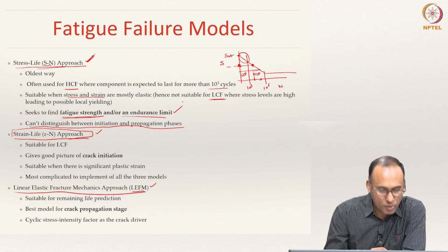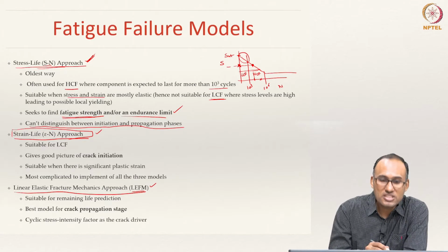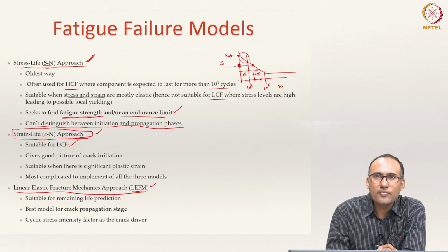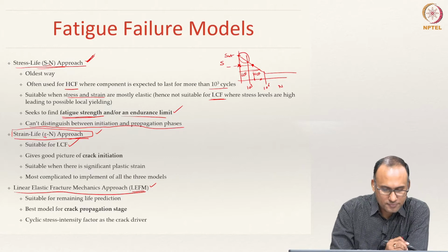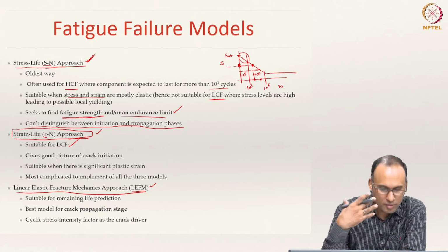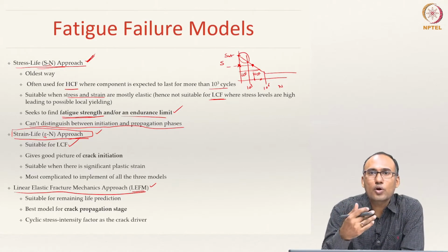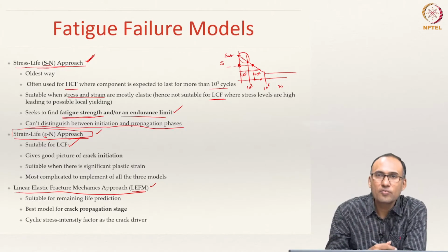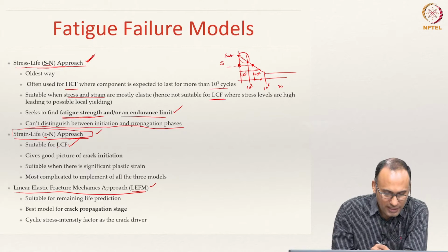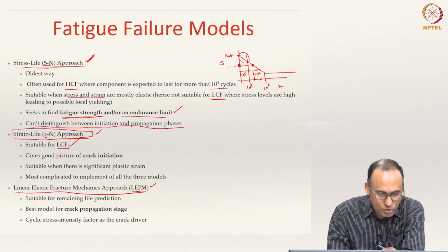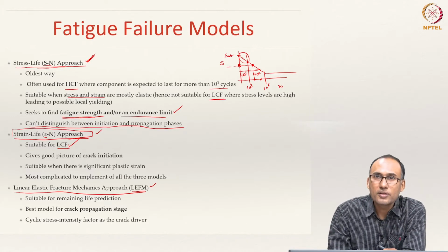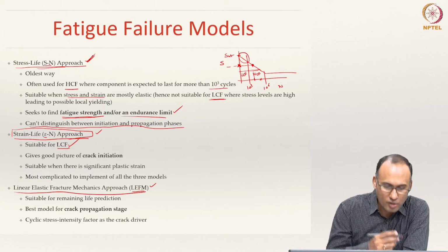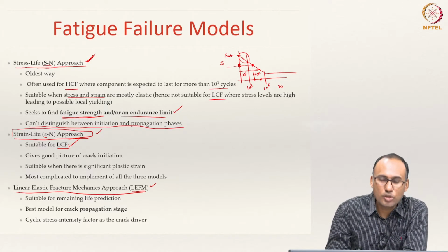And then we will talk about the strain life approach, which is perfectly suitable for LCF, because you are dealing with strain. You can explicitly figure out the plastic strain induced in the material. Based on the plastic strain we will be able to do the analysis, and hence it is very well suited for low cycle fatigue, because you can incorporate the plastic deformation into your model.